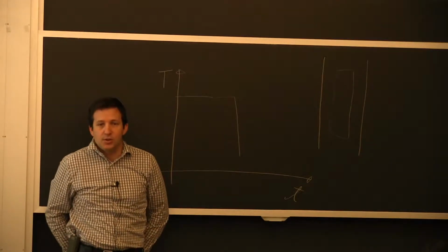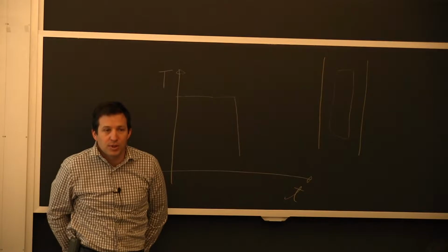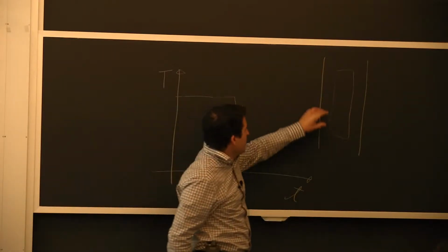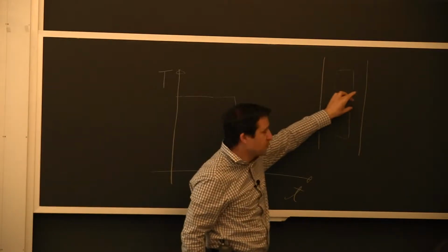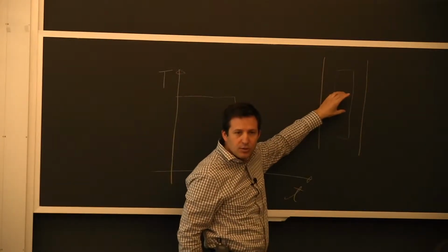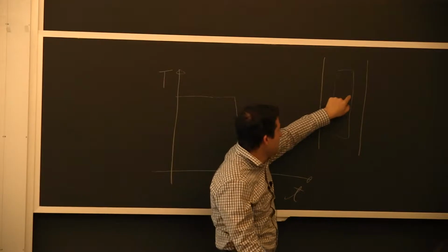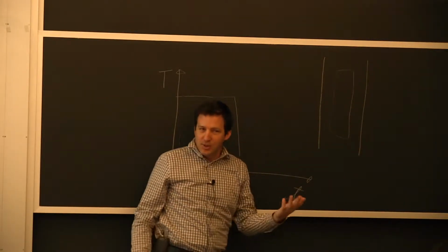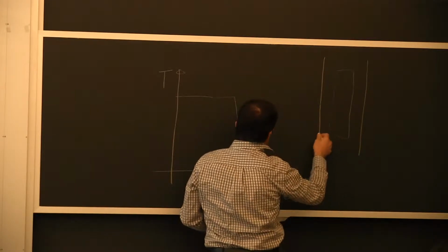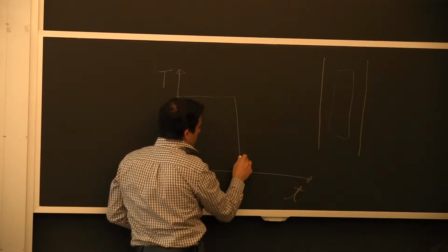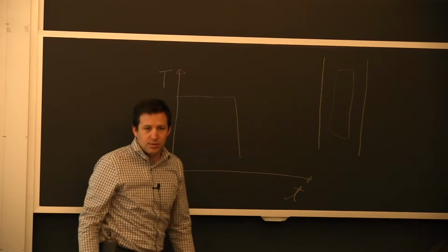It's the same way that you do tempered glass. You cool it down rapidly, and you deform plastically. You exceed the yield strength on the surface on each side, and when everything cools down, you're left with compression, tension, compression. It could be good or it could be bad. It depends on your application. So in the end product here, once you've quenched, you have these residual stresses.